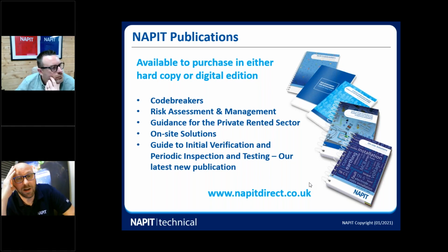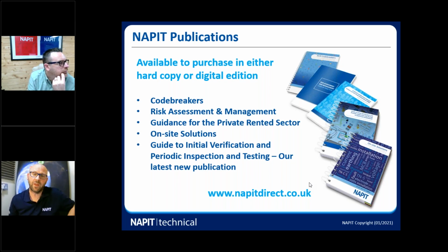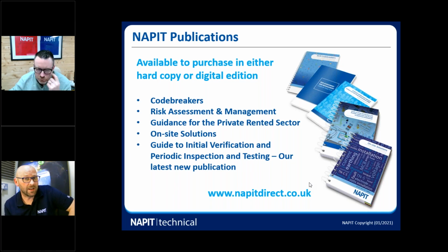So all you can do really is contact the DNO to see if they can check whether it's a dodgy joint somewhere and they can repair it and improve the earth. If not, if they disown it, you may have to be looking at other measures such as the installation being turned into a TT installation because the TN system is being deemed to be unreliable, in which case you need RCDs for fault protection, and it goes on and on. So it's not an easy question to answer without knowing the site specifics, but hopefully I've given you a good indication of what you should be thinking about.